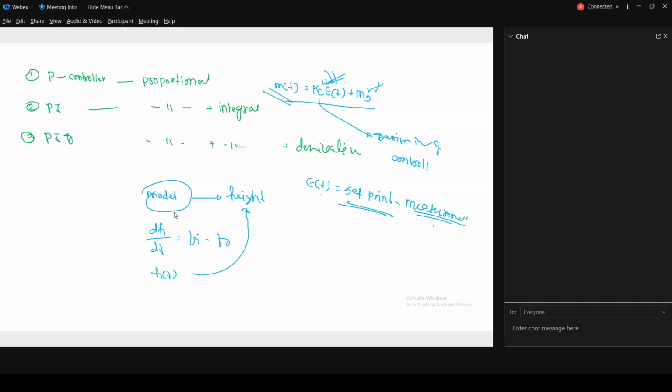So in this example, it's a percentage opening value. Initially, the steady state output is 5 meter and my set point is 7 meter, correct? And input steady state is 2 meter cube per second, for example. As soon as I give the set point, which is 7 meters, the error, epsilon of t, is 2 meter.